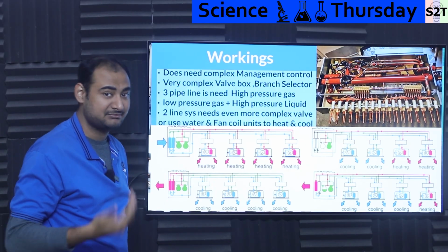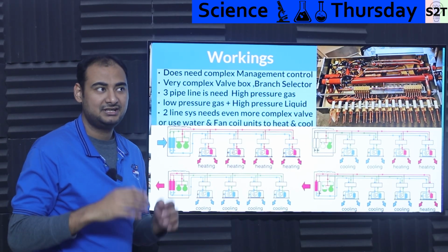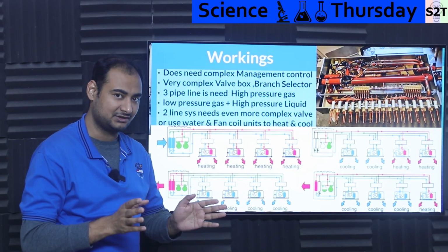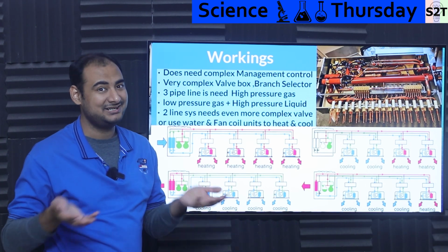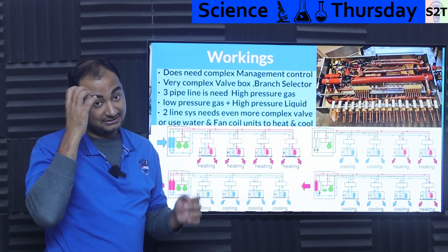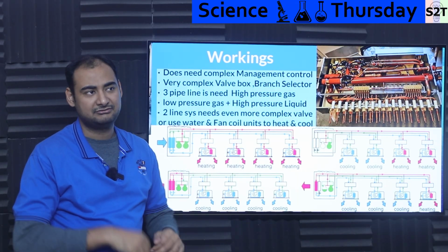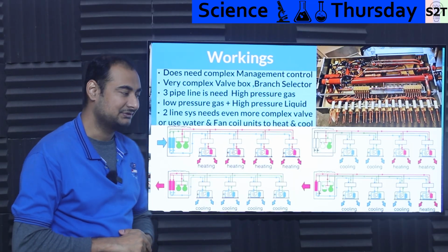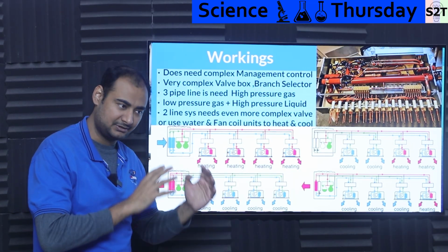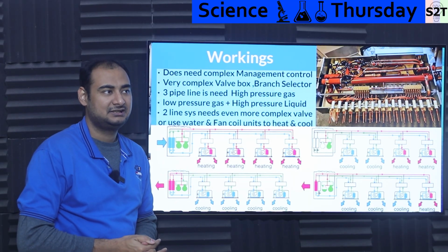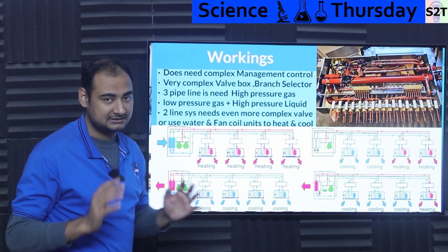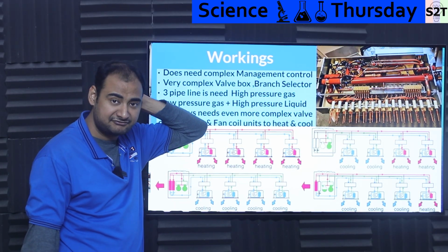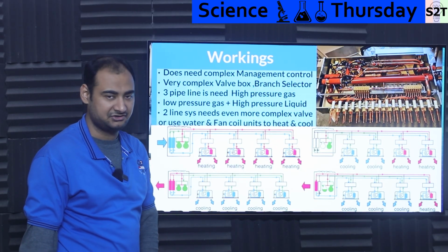Now generally these sorts of systems have multiple compressors. That's also another advantage. Many times it's not desirable to run a compressor at lower RPM. Compressors are fine tuned for one RPM, like one sweet spot. But what if your load is changing? Hey, what if you have multiple compressors? So you can have a scenario where compressor 1 goes full on, turns off, and compressor 2 takes care of it. Or if it needs to, both compressors could be running at 80%. That way, more time is spent per compressor being in the optimum spot rather than chugging along. So overall, yes, let that be clear: it does consume a lot of power and wastes some amount of energy in this sort of complex valve train, but it still gives you energy efficiency.